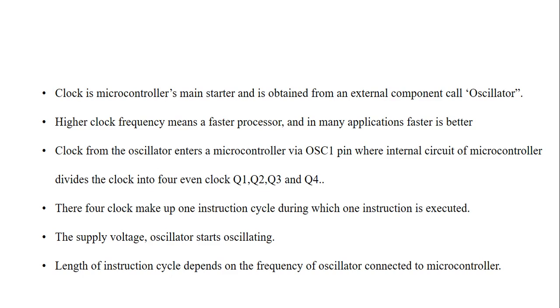Here I would like to give some examples: the sampling rate of the ADC, the baud rate of your UART, and the rate at which the timer runs. These are directly tied up with your system, and all these peripherals require synchronization as well as clock signals. So it is not possible to give an individual clock to each. The microcontroller gives the synchronization and clock signal to each of these peripherals.